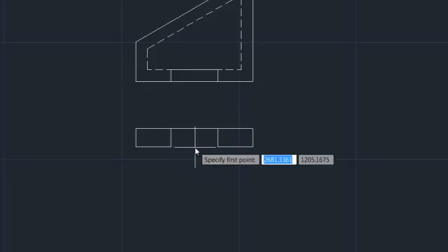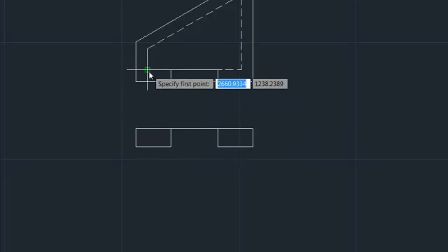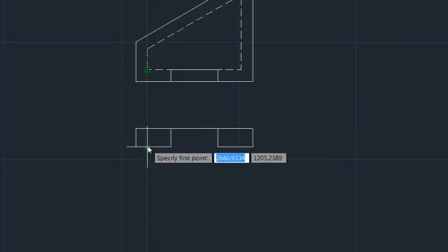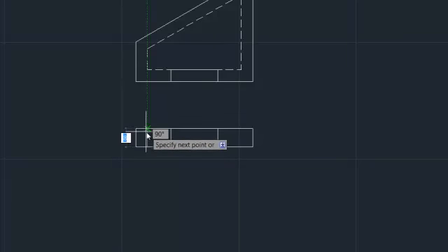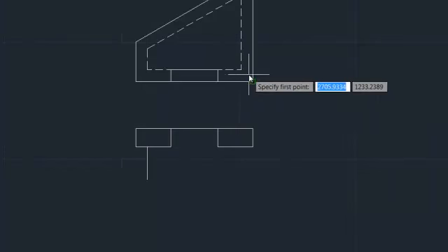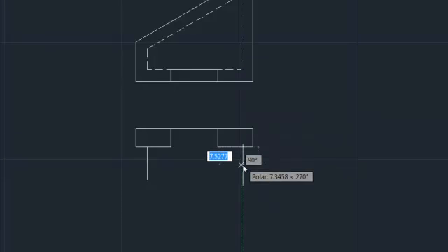Now we want to find the position of the lines on the interfaces, so we can use these hidden lines. Going down, it says on the side of the diagram it's 30 high, and the top and bottom bits are 8, so that leaves 14 in the middle. Again, we can do the same thing here, run this down, bang, 14.